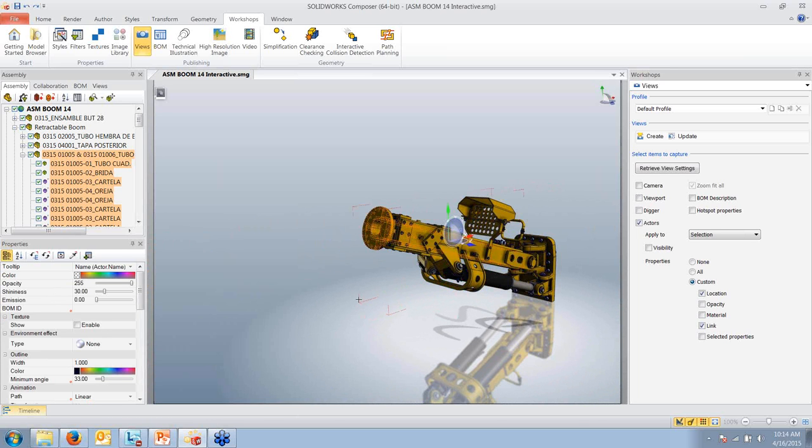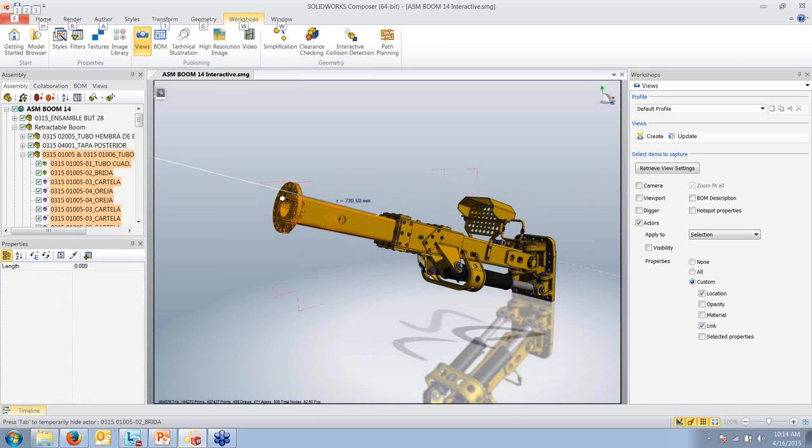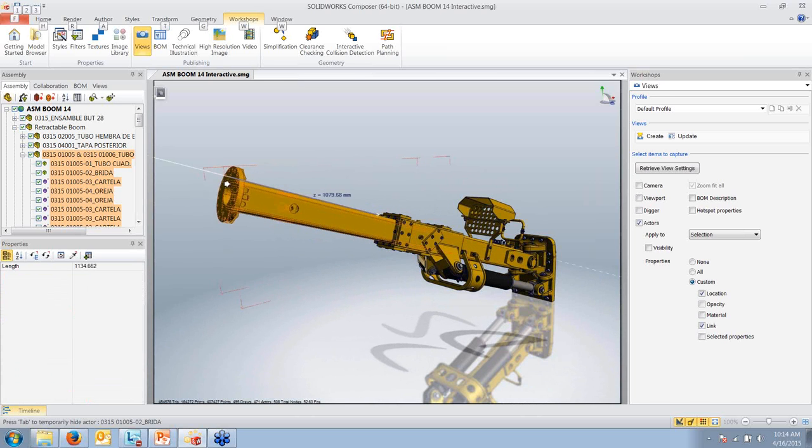So a really easy thing we can do to change where our gizmo is, or the direction of haul, is to hold down my Alt key. As I mouse over, I was picking up geometry references, saying, oh, you want to move it that direction, this direction. So I can just pick up a geometry reference from the part that's going the exact direction I want, click on that, and now it comes straight out like that.